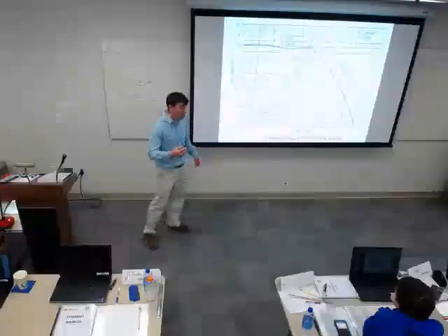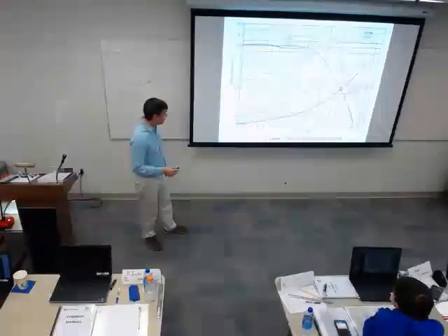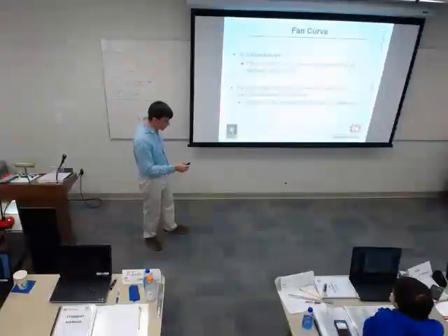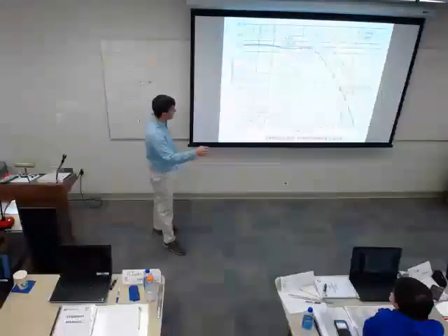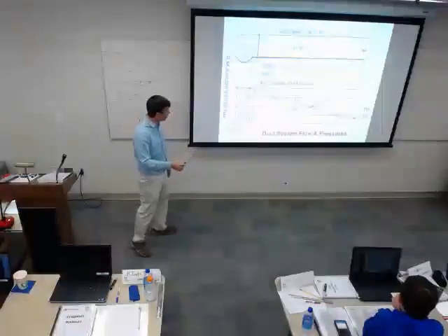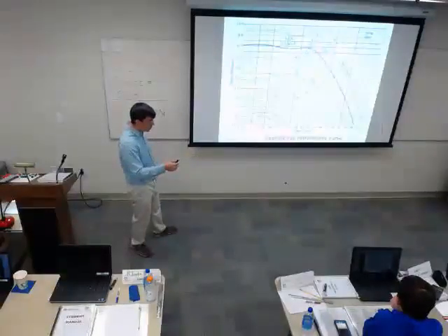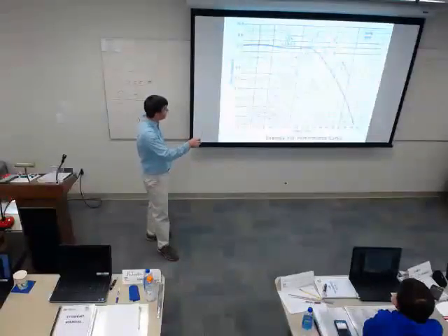So think back, we looked at what the pressure rise was across that fan. It was, I thought I plotted, sorry, it was 4 inches. I thought I had lines showing that, but we subtracted these two numbers, came up with 4 inches. So I can plot that. So I plot my 4 inches of static pressure on this axis.